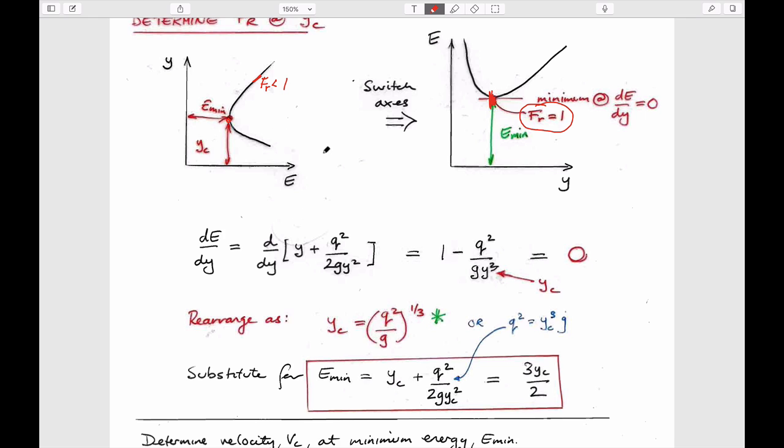because it's the ratio, by definition. This is the flow rate, this is the celerity wave magnitude. So if the flow rate is faster, then it's bigger than the 1. And so here, the Froude number is greater than 1. Here, it's exactly equal to 1.